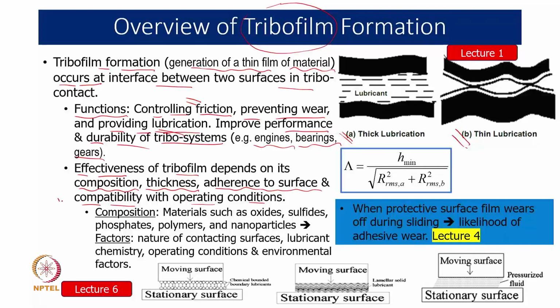Second, if we apply some sort of lubricant layer or tribofilm, and because of high temperature, high humidity, or some erosive particles the tribofilm doesn't remain, again the effectiveness will come down.